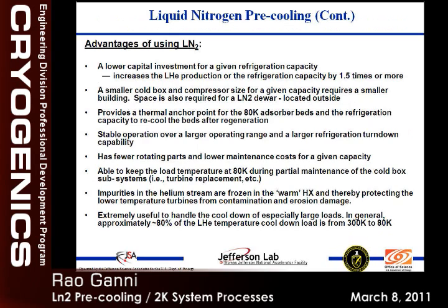So what are the advantages? It reduces the capital cost, because you are buying the refrigeration directly without the compressors and all these associated equipment. And if you already have a machine, and by providing liquid nitrogen, we can increase the capacity by up to 1.5 or more times depending upon what is a limiting component in that machine. So that means your capital, which you invested in the helium system, is able to produce twice as much by using nitrogen. And a smaller cold box, because you are buying the refrigeration from outside, and although we need a dewar, we normally put it outside, so we don't need that bigger room.